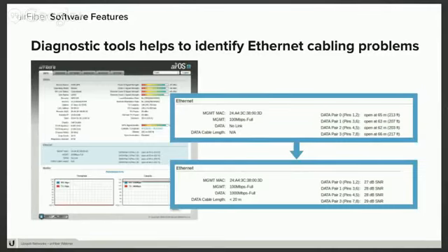Again, on the bottom we have a similar link, but this time we're actually connected up. You can see that the cable length is less than 20 meters, so this particular one is very, very short. On the right, you see the relative signal-to-noise ratio that the transceiver, the chip that decodes inside the radio, is actually seeing. This is the signal-to-noise ratio seen after the internal AGC. So it's a relative number, but it tells you what the chip is seeing. At 28 or 29, I believe, is as good as it gets. Typically, you'll see numbers in the 28 range for links where you don't have any sort of issue with the cable.